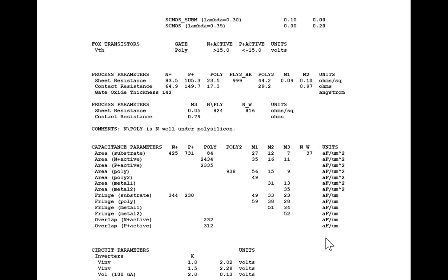We're going to see that there's a capacitance formed between the N and the P-type material on the bottom. We're going to also find there's a capacitance formed on what's called the sidewall. So the total capacitance along the sidewall will be the capacitance per unit length times the perimeter. The capacitance on the bottom is the capacitance per unit area times the area. So these have to do with fringe capacitors that are on sidewalls of devices.